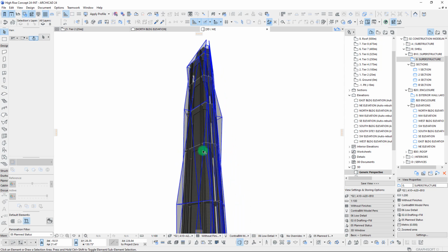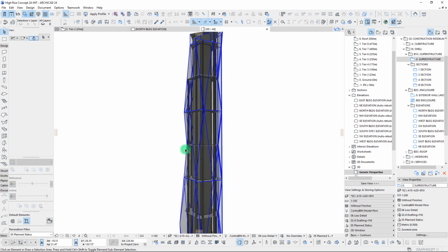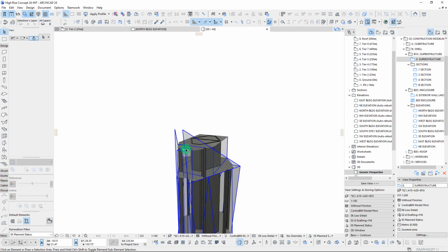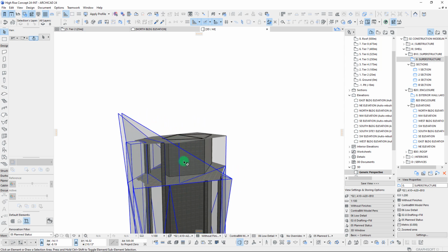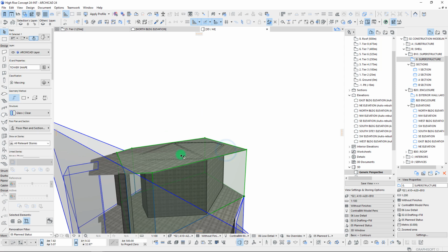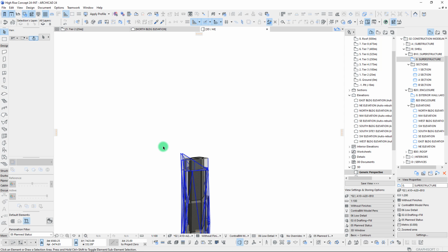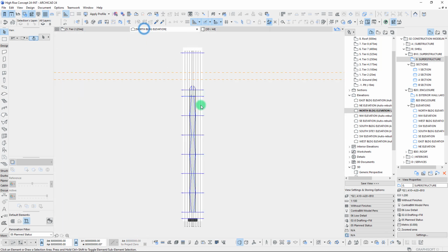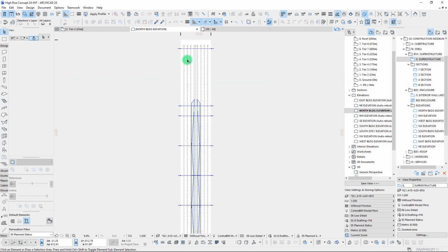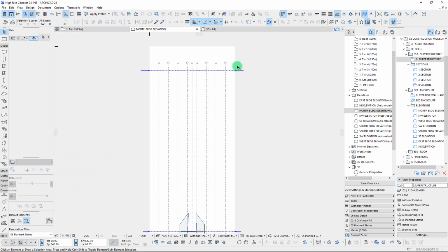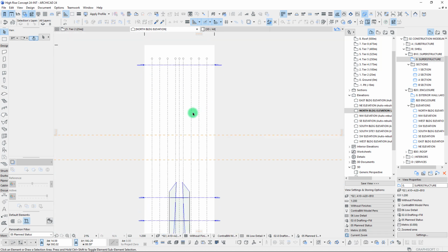Okay, so now that we've got the facade on, it's time to pretty much cap this thing off by adding in the spire. That's going to take us from our level 500 meters here, all the way up to 644 at the tallest point of the building. So in order to work on this, let's start with just taking a look here at our north elevation. Just to reiterate, we're at 500, trying to get up to that 644 point.